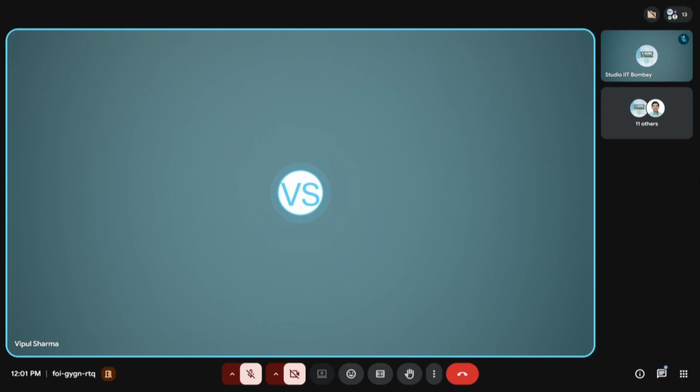But specifically in this kind of scenario where we have a limitation, we are not building it for a product, we are building it for our own learning and our own satisfaction. I want to get the experience of taping out a design and being able to measure it. So if you try to follow each and every step to the point, you will consume a lot of time doing a common centroid layout to ensure the matching, etc. In that case, you might miss the window of submitting your design. I'm talking about this particular scenario.